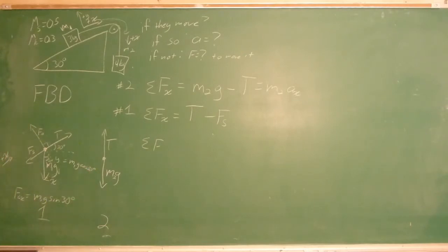If you're confused about that, double check our vectors, make certain that you draw it out. We'd have a situation where here's mass 1 times gravity, that's my magnitude, my total length. I've got a y component here, and an x component here, with an angle of 30 degrees, and then solve for your y component and your x component. When you do that, you should end up with the y component equal to the magnitude, mass 1 times gravity, times cosine, because that's our adjacent side, 30, and then the opposite side, our x component down here, will be the same thing with sine instead.